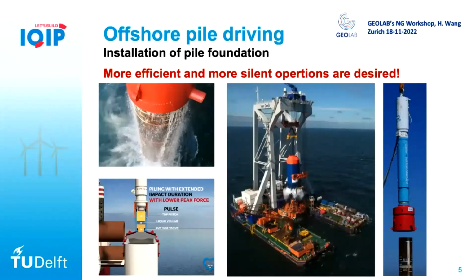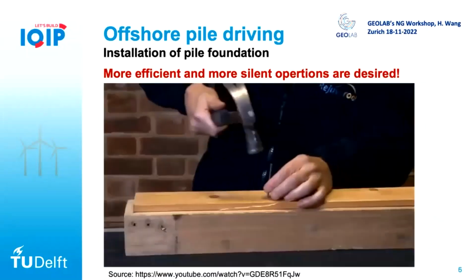Traditionally people install the pile foundation using this hammer system, and it was not a problem before for example on oil and gas platforms because you don't have so many pile foundations. But once you come to the offshore wind farm, certainly you are going to install hundreds of monopiles. So then you need to think about how can I improve the installation, because that's basically money related.